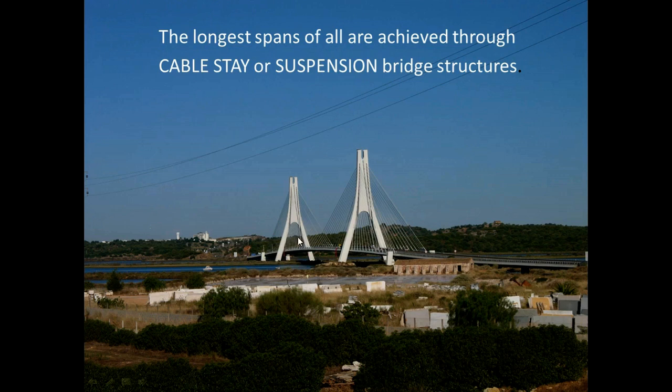so that you're lightening the load. So here we have a cable stay bridge, and the difference between a cable stay and suspension we'll show you in a minute, but suffice to say, of course, you need the height again, because you're effectively hanging the deck of the bridge off these two masts here, aren't you? All the load's coming back through the wire to the mast and then back down to ground again.